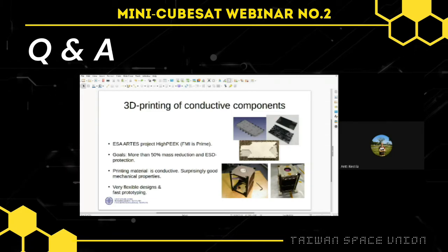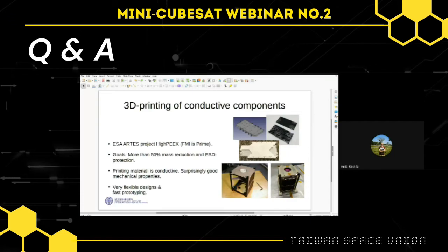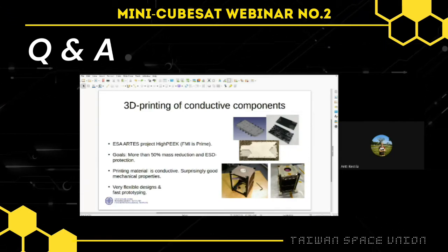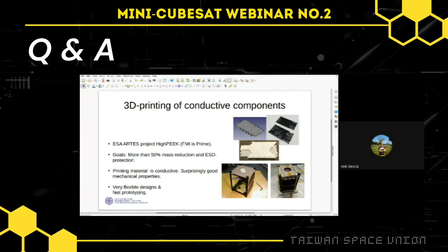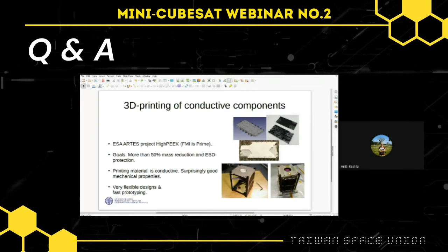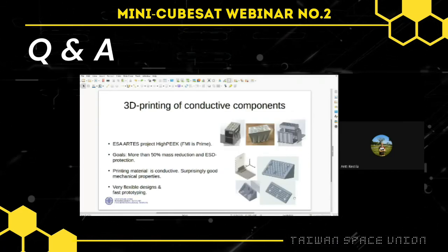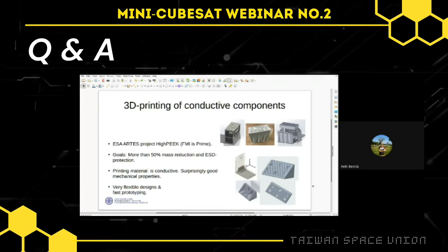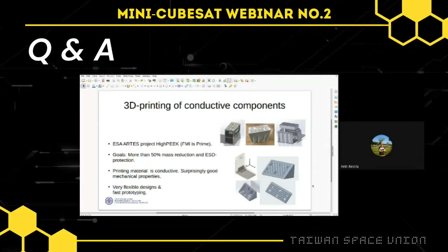Yes, it's another good point. One of the surprising elements when we tested these with the vibration bench is that people's first idea is, okay, they're plastic, so they probably won't withstand that much. But they can. We have tested this antenna part in a shaker test, a vibration shaking test, and the earlier parts too. All of these parts we have tested on a vibration bench. These parts we tested about two weeks ago, and they were able to withstand it without any kind of hitch or problem.